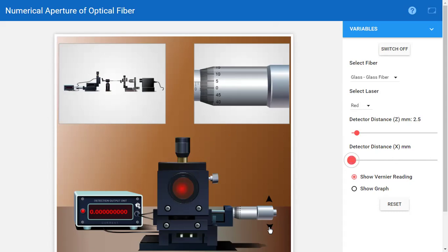As you move this, you can see the current will not come immediately. You can see here I am moving, using this knob, the downward arrow mark. You can look at this ammeter. No current is coming. Like this, current starts later. That's why current is zero up to certain readings. So you have to take readings tactically. You go on rotating the head scale of the micrometer by 20 divisions, then note down the ammeter reading.